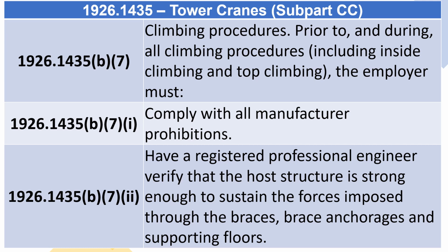1926.1435(b)(7), Climbing procedures. Prior to, and during, all climbing procedures, including inside climbing and top climbing, the employer must: 1926.1435(b)(7)(i) and (b)(7)(ii), comply with all manufacturer prohibitions, and have a registered professional engineer verify that the host structure is strong enough to sustain the forces imposed through the braces, brace anchorages, and supporting floors.